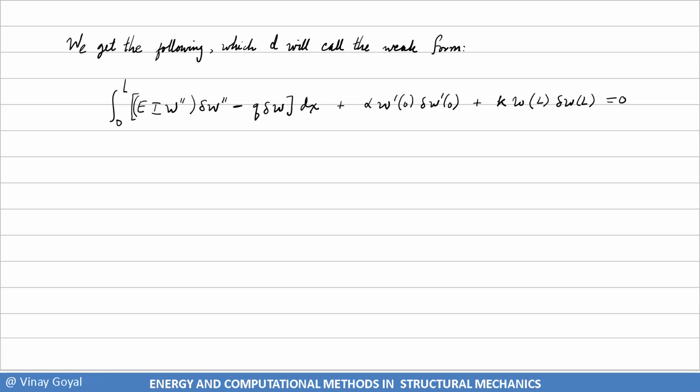So I get this. So to form the functional is very simple. Anytime you see the W repeated like that, you're going to turn that into 1/2. And so that's how you construct the functional. So now the functional can be constructed as follows: integral from 0 to L of 1/2 EI W prime, and we're going to make this del W prime into W prime, so you get W prime, minus Q W. Anytime you see del W, you're going to convert it into W alone.